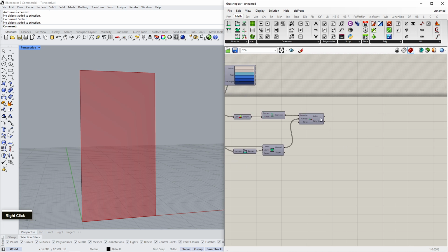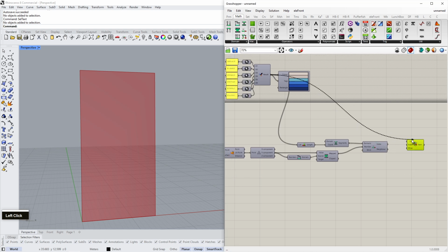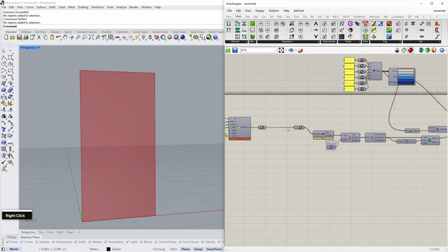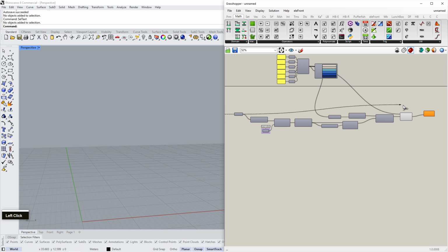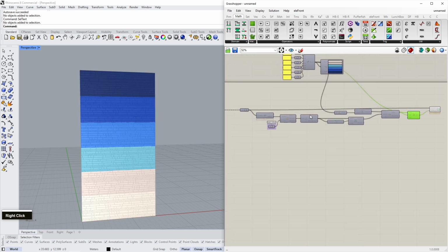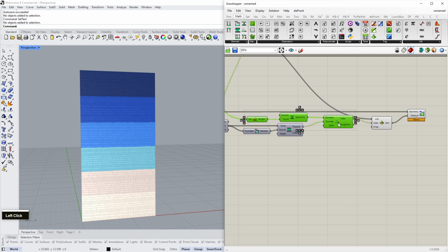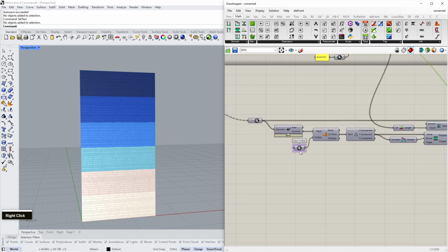So supposedly if I list item and my list of colors, and then the index like this, if I preview, these are all the colors, and then geometry is our flattened list here, connected here. You see that I have, based on the y value of my UV point, I kind of applied the color to it, right?